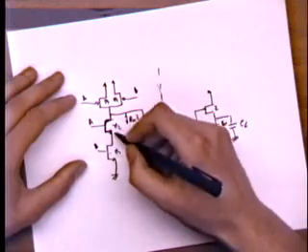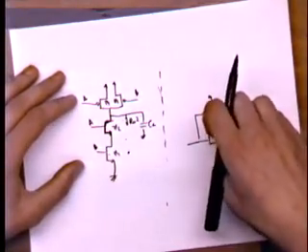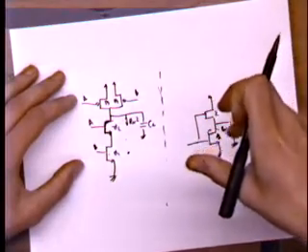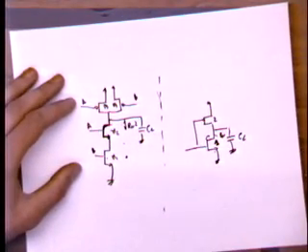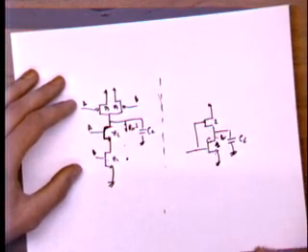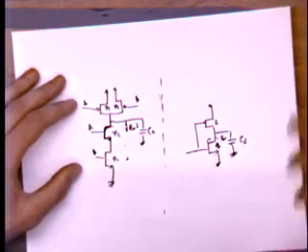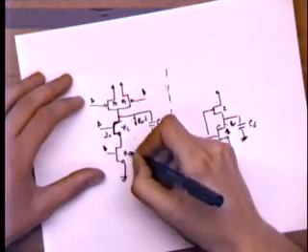So what we do is we do Rn of these devices to the left, half of Rn of the inverter, okay? Which means that we make their width twice as large as the width of the inverter, okay? There's two transistors in series. The worst case is when both are on. Therefore, the worst case resistance is twice the resistance of each of them. Because we want the total resistance to be constant, then we just decrease each of these resistors' value by the same amount, and we make it half each, right? And so this is 2x now, and this is 2x.